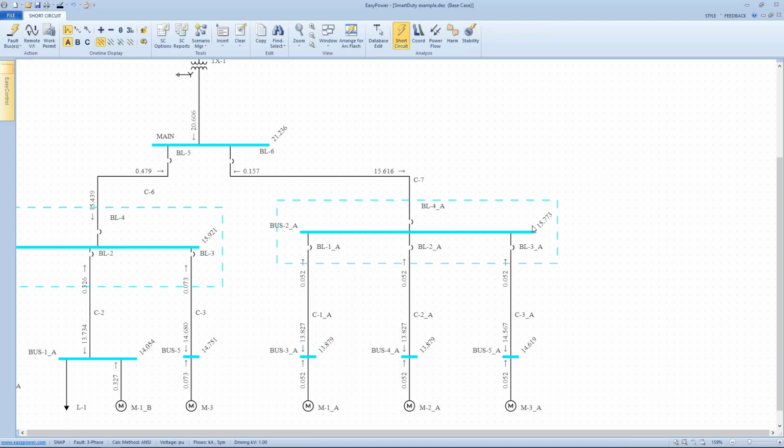And if you look at the quantity that would remain if we took 15,773 and subtracted the 52 amps that are being forced as feedback, then this breaker has to handle that much current in reverse, if you will, as a fault, if the fault were to exist just below the breaker. So that's why this breaker is not properly meeting its short circuit rating. And frankly, it's the weak link for this whole bus.